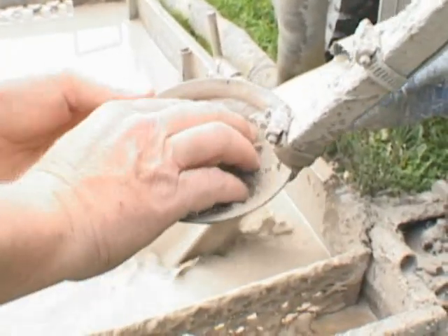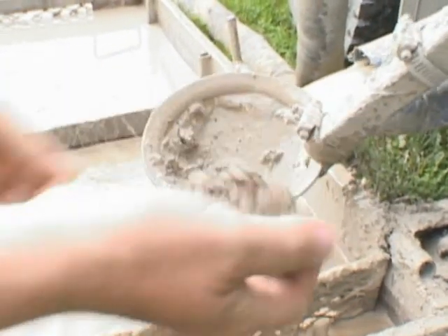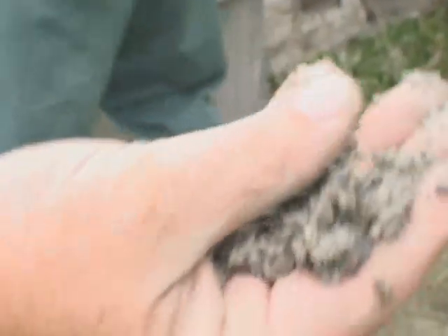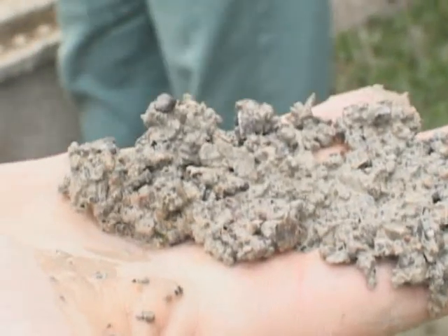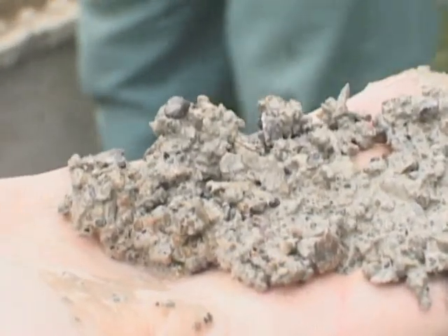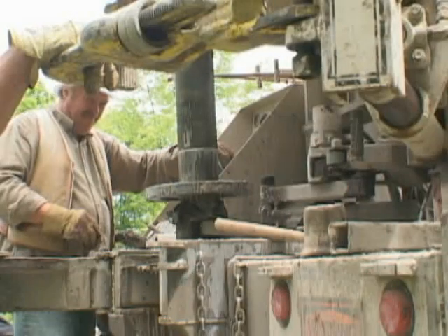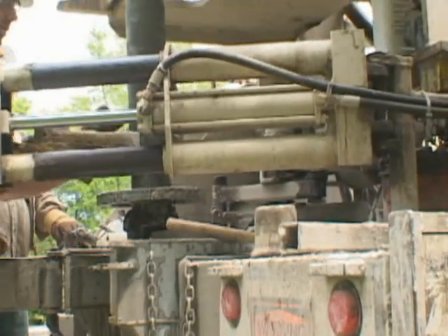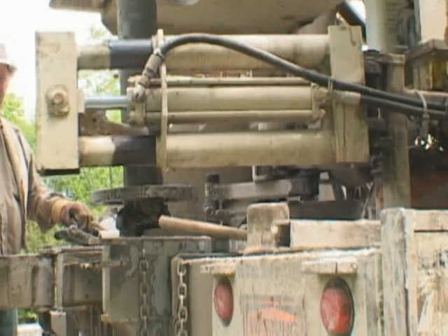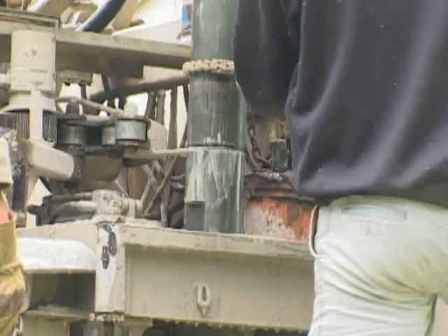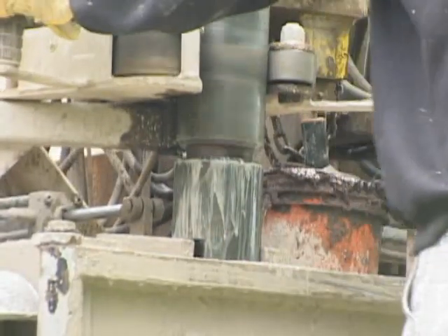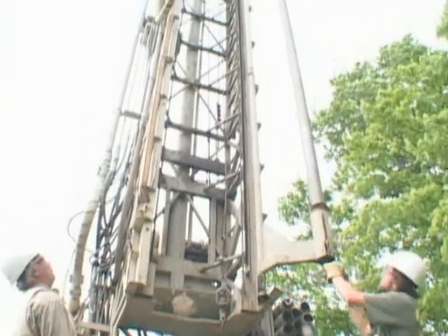Accurate identification of the cuttings is made difficult due to the masking effect of the drilling mud. Larger cutting samples are more easily gathered. The smaller cuttings are contained within the mud mixture and are more difficult to identify. This particular rig has hydraulically assisted functions designed to minimize operator fatigue and improve efficiency. These include a breakout wrench, a powered fork, pipe spinners, and rod carousel.